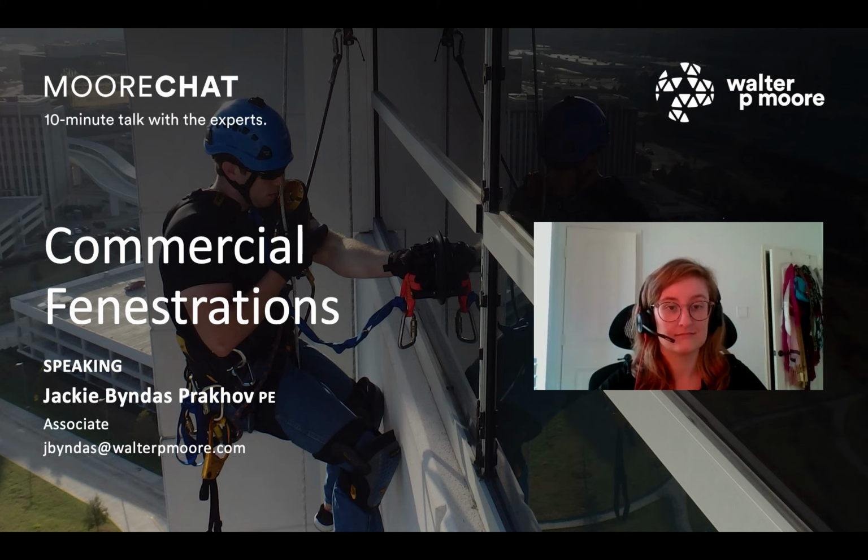Hey, Jackie, thanks for the presentation. I had a question about construction issues. What would you say are the most common construction issues you've come across for the 3 fenestration systems you went over? That's a great question. So for storefronts, I would definitely say that the end dams. So you have your sill pan in your storefront systems that your frame sits on, and then your end dams are exactly how it sounds, at each end.